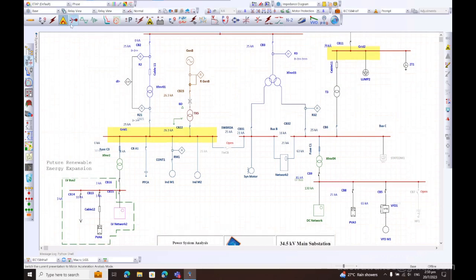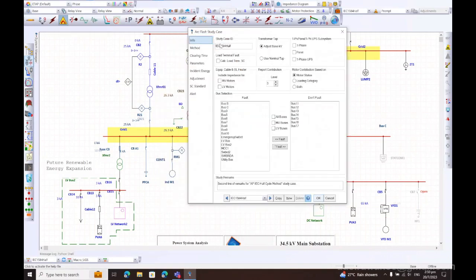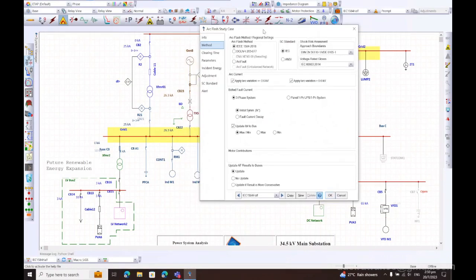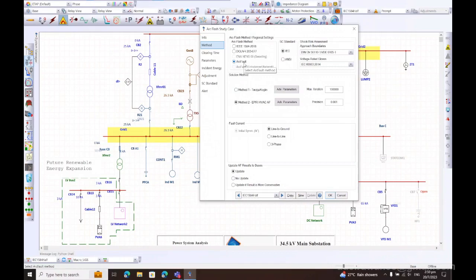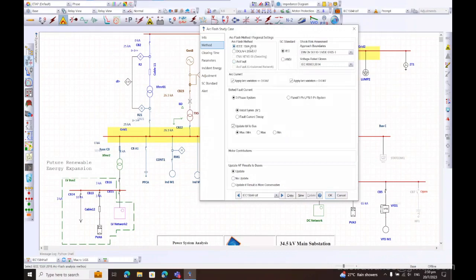The arc flash calculations look at the PPE requirements, like what the incident energy is. For example, I can run it in ETAP. We provide various standards you can choose, like IEEE 1584. If you have a system of more than 15 kV, for example, you can also use the arc fault methods in ETAP. So let's look at just one example using the 1584 standard.